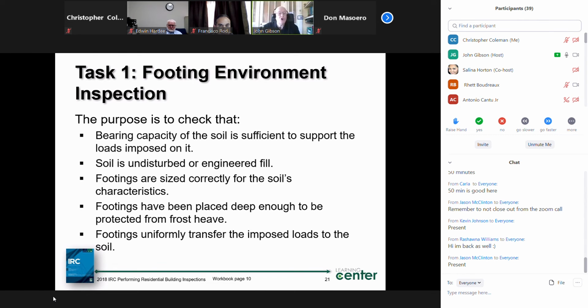You're out of the scope of using the engineering for the IRC. And you would have to now treat it as an IBC structure. And some of y'all deal with commercial structures. When we go to the IBC, I'm looking for type of construction, and I'm looking for, again, a classification of the occupancy group. So it'd be like an R3, for example. And if you still want to use, for example, wood framing, light frame wood, that would be probably a 5B structure as an R3 per the IBC and how you're going to build it.